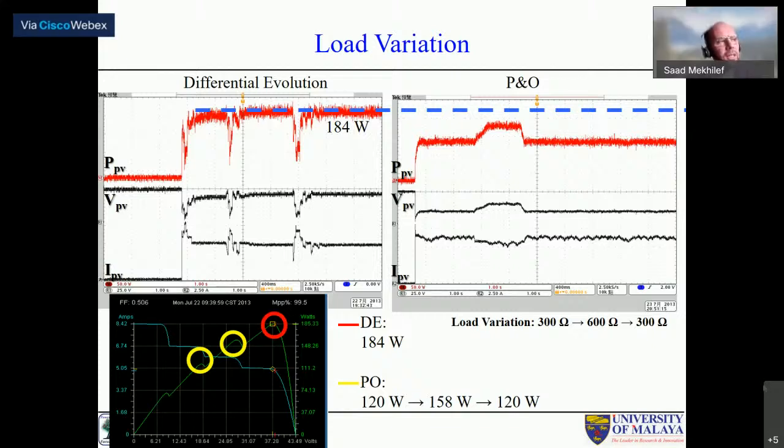Actually there are a few methods which can be used to avoid the problem of partial shading, which affects the hotspots on the PV panels. The traditional way is the diodes, where we group a number of cells and then put a bypass diode to minimize the impact. But there is new research looking into voltage equalizers, and how to balance the power between the cells using MOSFET switching. But still in the commercial ones, diodes are the most commonly used. Yeah. Thank you, sir.